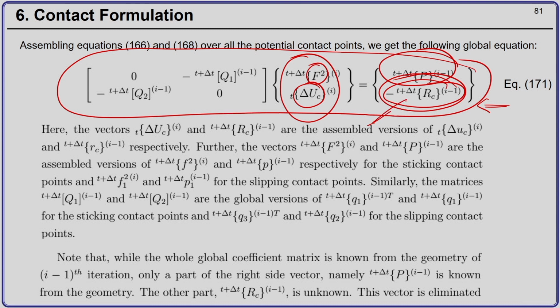So, this is a global unbalanced force vector corresponding to the contact nodes, and when we add this with the Newton-Raphson iteration we can eliminate this over here, and then you will get the tangent matrix K of two bodies here. In that case you can solve for the unknown contact displacement and the contact forces.